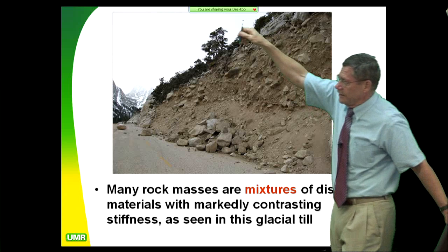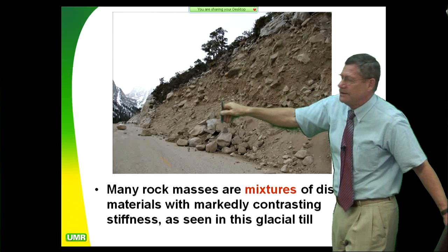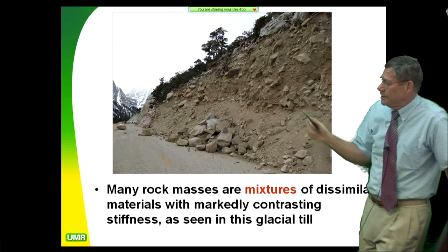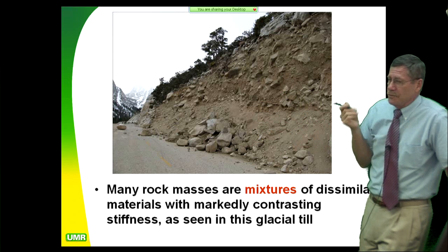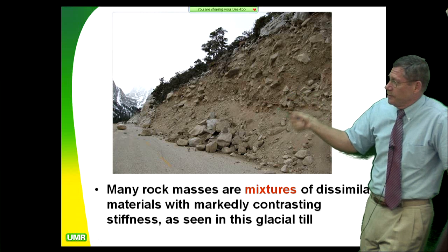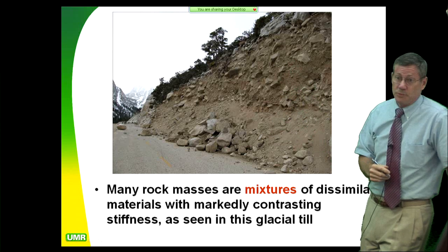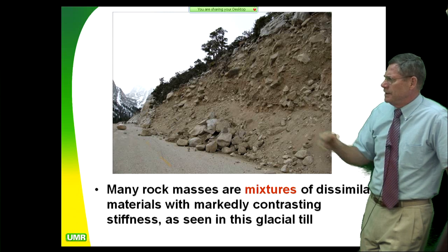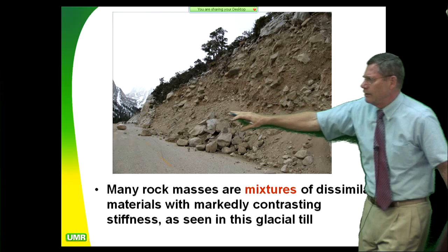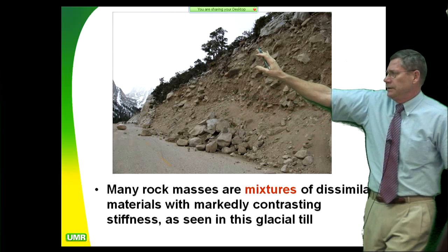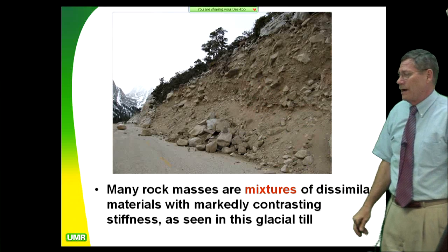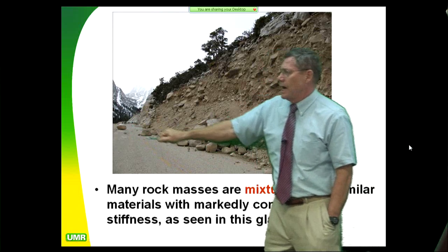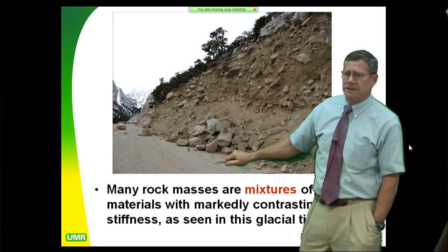So if you drill a hole here, can you drill a hole in this kind of material? No. Then how do you come up with strength parameters? Through back analysis. Look at the slope. How steep is that slope? It's pretty steep, Bob. How high is it? Well, it's pretty high. But these materials are plucking out when you have a lot of moisture, a lot of rain on it. This kind of a road is going to be a very high maintenance, high hazard road.